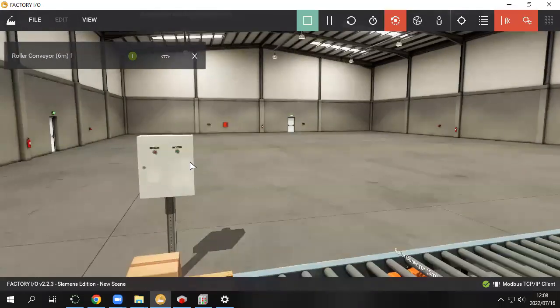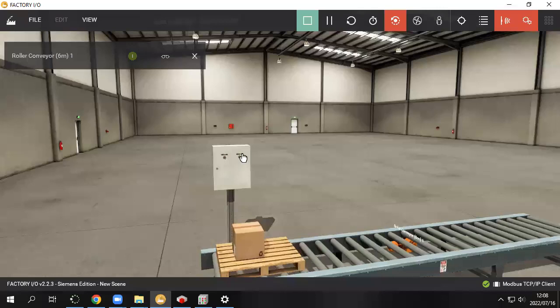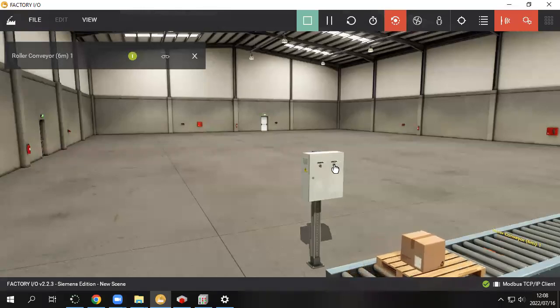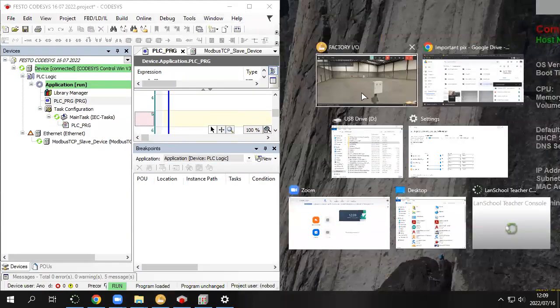This concept, people don't understand why we are putting in latching loops and relays. When you start a PLC, this is the most important code of all. You press your start button, your machine moves, you let go, and it stops. So now you need to make it keep going until infinity, basically. Let's see what happens when we press the start button.